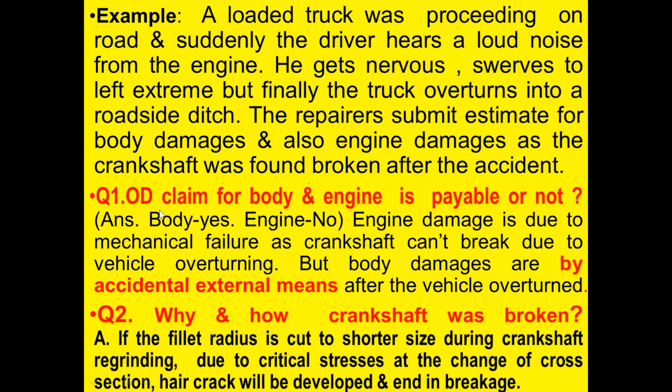Now the question: is the OD claim for body and engine payable or not? Answer: body yes, engine no. Engine damage is due to mechanical failure, as the crankshaft can't break due to vehicle overturning. But body damages are by accidental external means after the vehicle overturned, therefore payable.